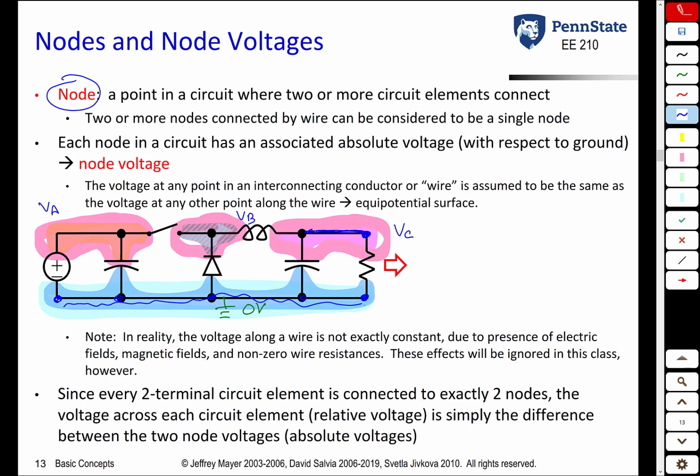So the first thing you see when you have a circuit this way is you can simplify how it's drawn by collapsing the nodes. For example, all of these points on the bottom, even though it looks like they're separate nodes, it's really one node. So you can draw it as one dot there. Likewise, we have a node there, and a node here. And so between here, you have the voltage source, and there's a capacitor. Then between this node here and this node, you have your switch.